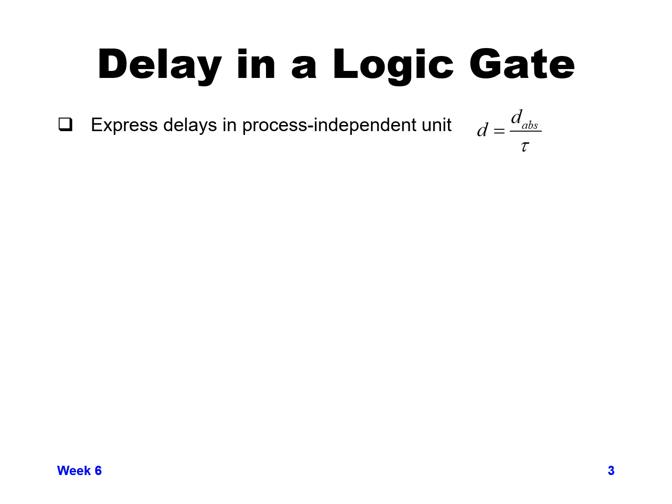the concept of the absolute delay, D sub abs, which would be like how many picoseconds or nanoseconds or whatever it is that we're measuring, divided by a process dependent term called tau. And that way we'll get a normalized delay, a delay in terms of number of delay units for a given process. So for example, I said several slides ago that the delay through a minimum size inverter on a given process with no load on it has a delay of 3RC.